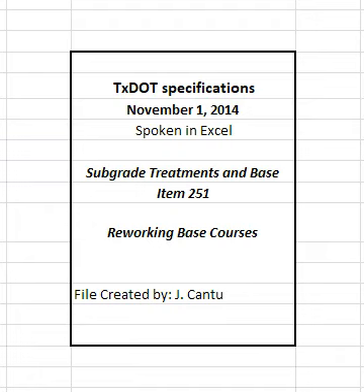Scarify existing material for its full width and depth unless otherwise shown on the plans. Do not disturb the underlying subgrade. Break material into particles of not more than 2.5 inches unless otherwise shown on the plans.